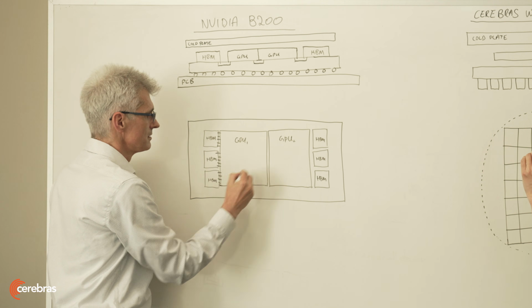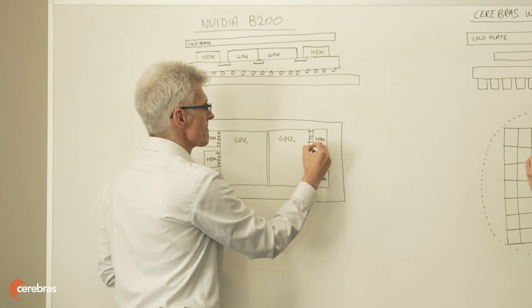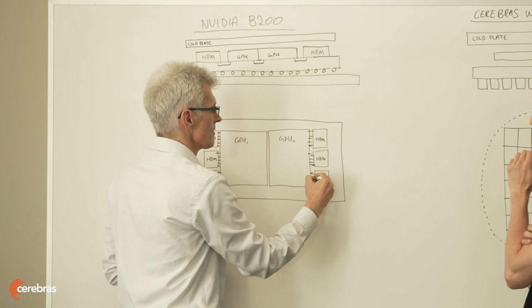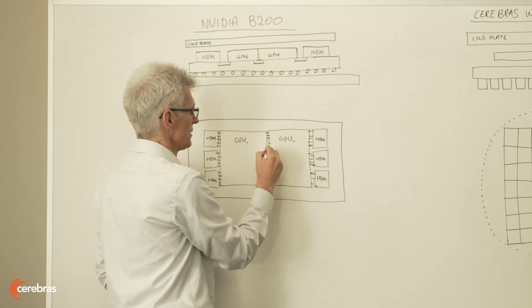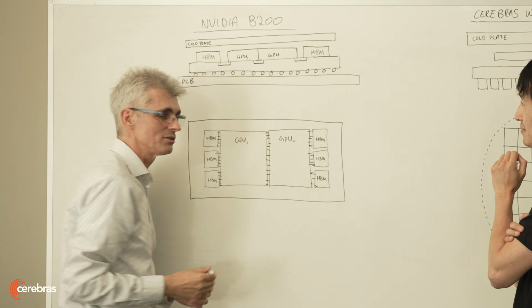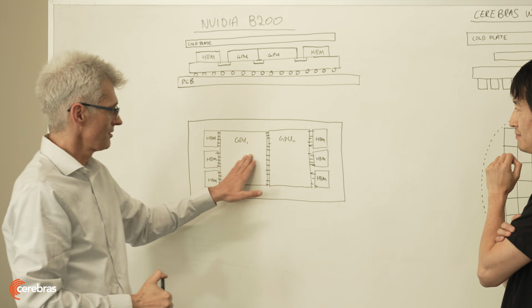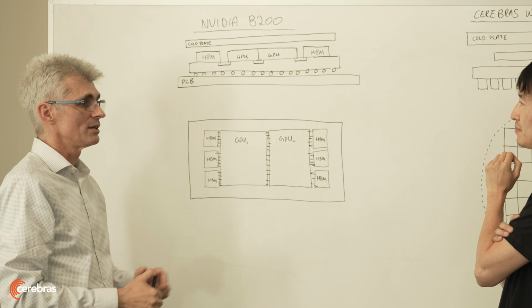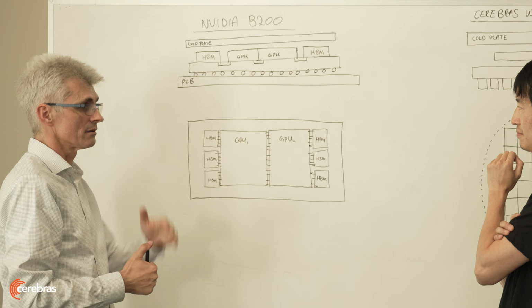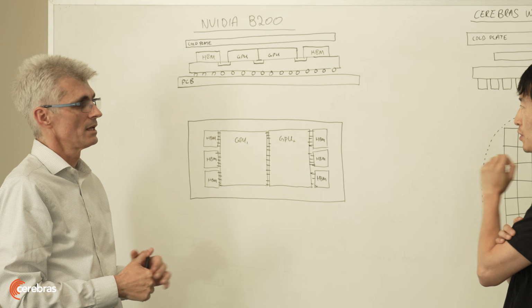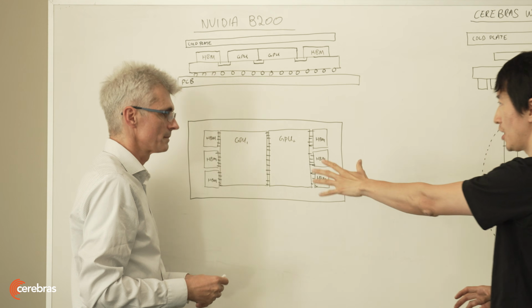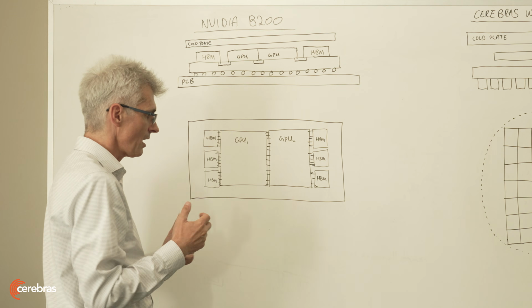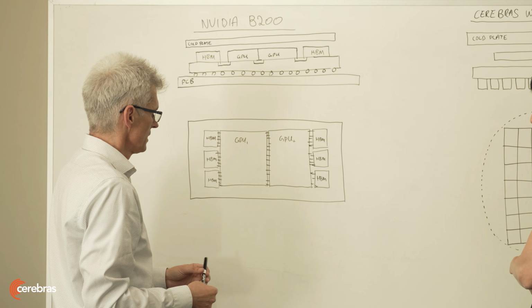Now, what is different with the Blackwell generation for this layer versus previously with H100? This is different. The middle? You now need to interconnect these two logic die with a very high number of interconnections between them. So previously only logic to memory, now both logic and logic. Yeah, so you need a very high number of interconnections.